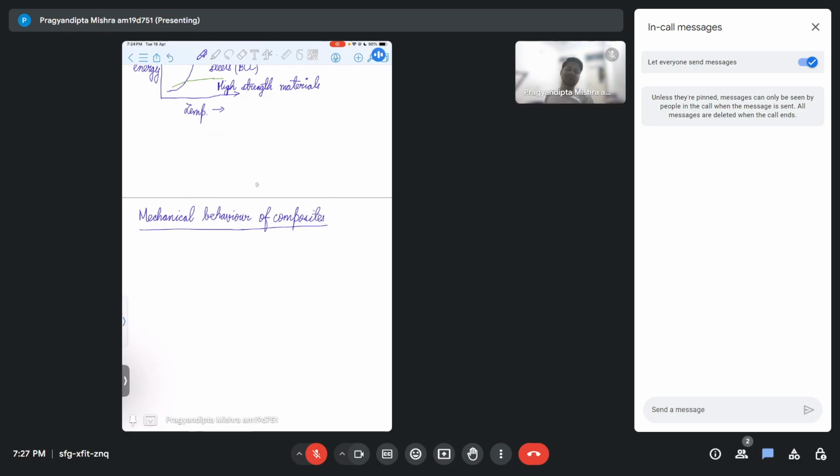So here, since we are looking at mechanical behavior, in most places we want to ensure that the elastic modulus should change significantly. Therefore, if you see things like adding one metal into another metal, you will form an alloy or you will form precipitates, etc. They do not come under the purview of composites, because essentially the elastic modulus does not change significantly. So that is one important criterion that you have to keep in mind.